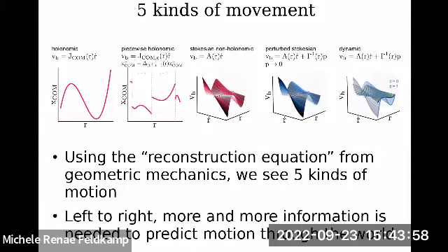But the next thing you can do is what we humans do when we walk. It's a piecewise holonomic system. While my left foot is planted, I can do that calculation. Then I plant my right foot and I can do the calculation again. But now I'm back to the same shape and my center of mass has moved. So as soon as you become piecewise holonomic, you can start having motion.